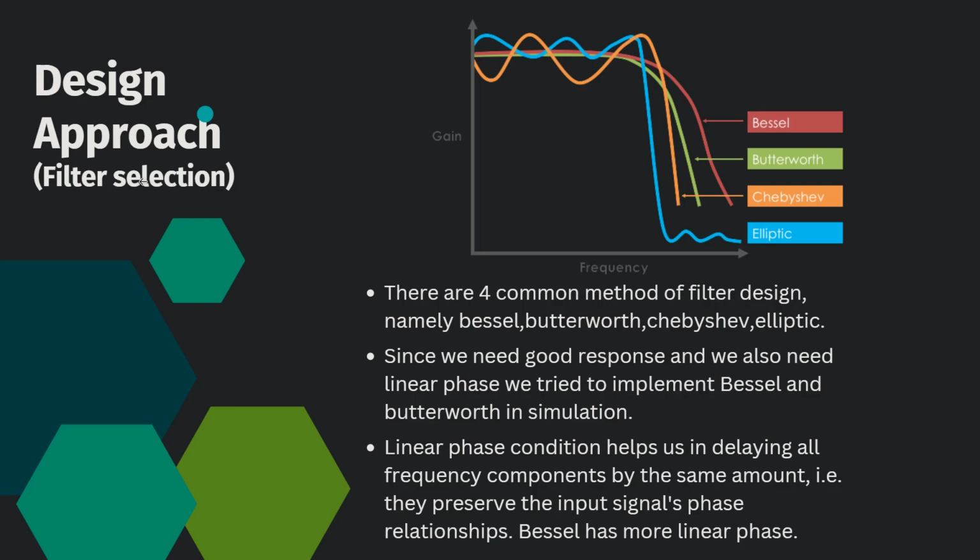Now moving on to our hardware implementation, we implemented our circuit in two ways, the breadboard and the PCB as well. So we need to choose a range of 0.5 to 100 Hz, and we used a UA741 op amp for our hardware implementation.